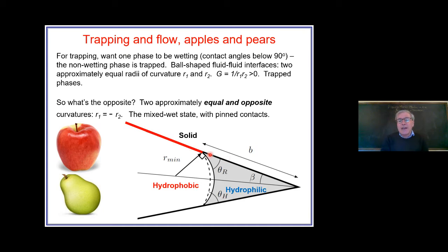So something that, for instance, here would be a carbon fiber in a fuel cell, and a carbon fiber that's coated with plastic. And at the interface here, the contact angle is actually changing as I change pressure, but it's pinned in place. And the reason is that if I've got water here, it doesn't want to go across that. It's repelled from that surface. So the three-phase contact is pinned in place.